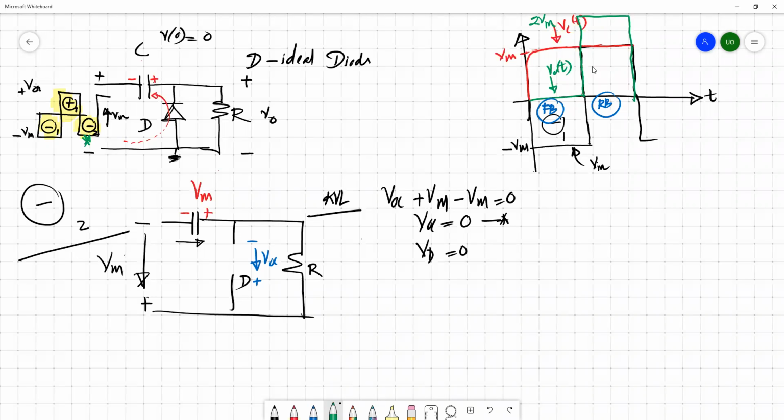So then the input is something like that. So we have a negative input. So this capacitor remains at Vm because during this previous cycle the diode gets reverse biased, and whatever the circuit brought up is like having a high RC constant, and this capacitor doesn't have a chance to discharge to the resistor we introduce because this time constant is high. So then we argued that whatever the stored voltage across the capacitor remains as it is.